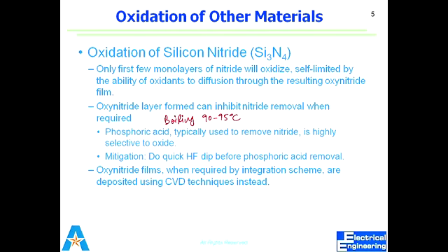Let's suppose we are following a protocol where we are using HF. So in HF, if we are masking something, if we are using oxide as the passivation layer, in case of an HF process, the oxide layer cannot be used as the mask. So we will go with silicon nitride, because silicon nitride is not affected by HF, but silicon dioxide is removed by HF. So depending upon application, sometimes we introduce silicon nitride instead of silicon dioxide as a passivation layer or as a hard mask.